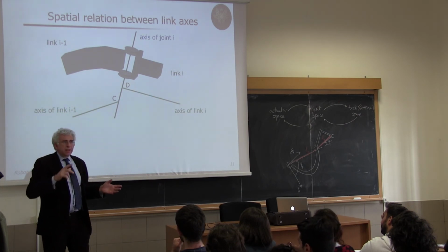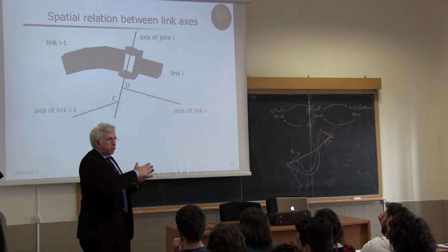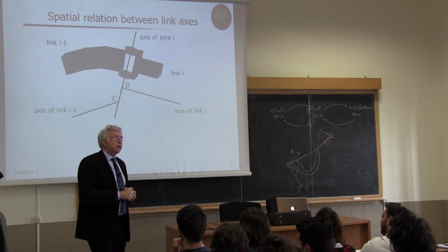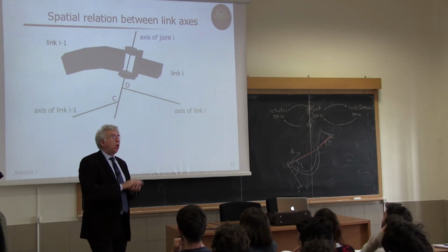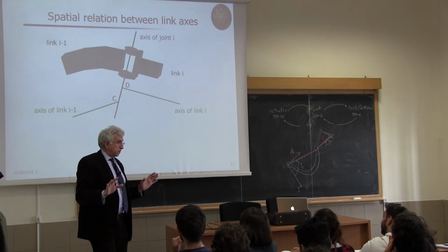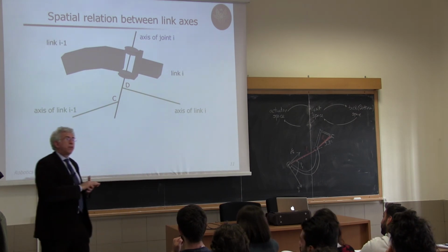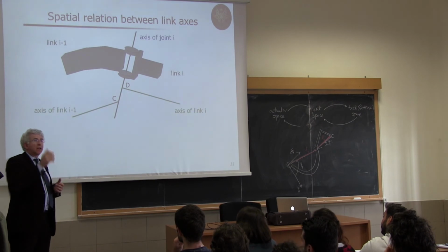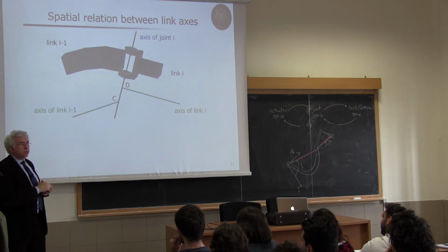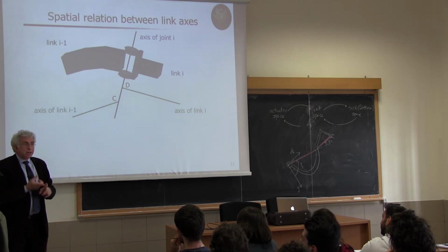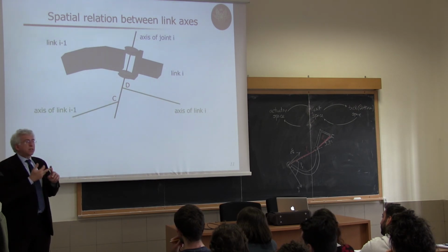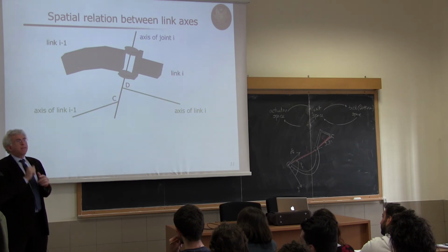And remember that those two variables, when we describe a kinematic chain, will always be constant, by the very nature of the fact that the robot has 1 degree of freedom joints. While here we'll define again one distance and one displacement and one angle, but this may vary with the configuration.